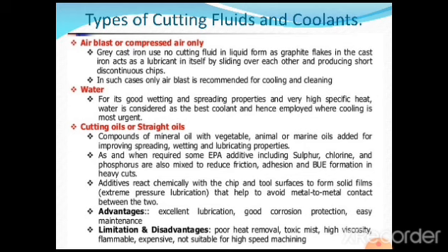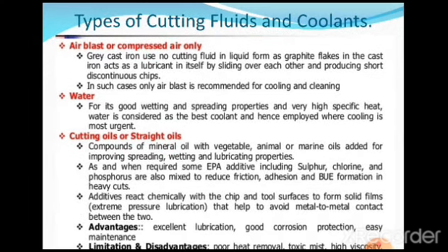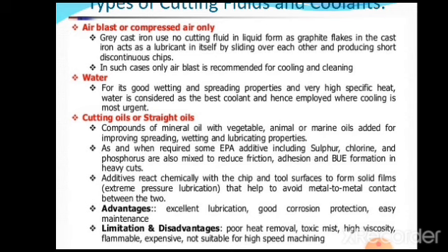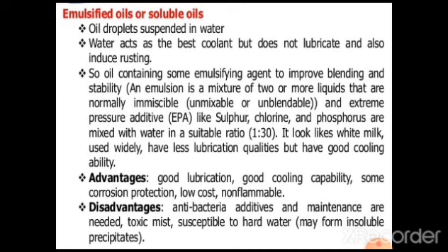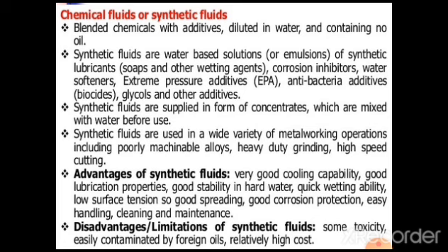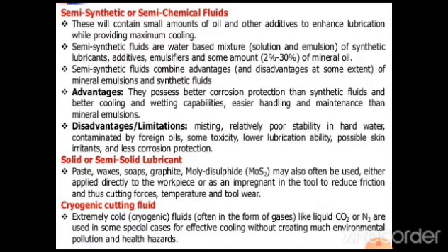The next one coming up is the types of cutting fluids. In types of cutting fluids, you can have air blast or compressed air only. You can have water, cutting oils or straight oils, and emulsified oils or soluble oils. Chemical fluids or synthetic fluids, semi-synthetic or semi-chemical fluids, solid or semi-solid lubricant, cryogenic cutting fluid, like this. But before I proceed, I will be telling about the importance of this.